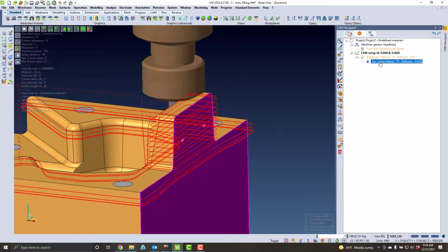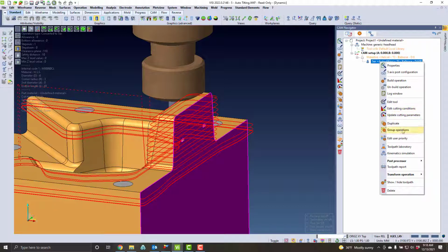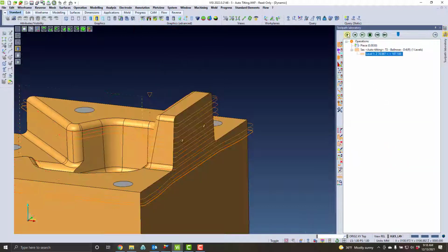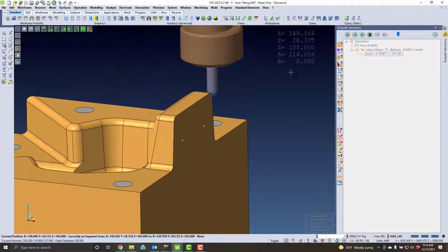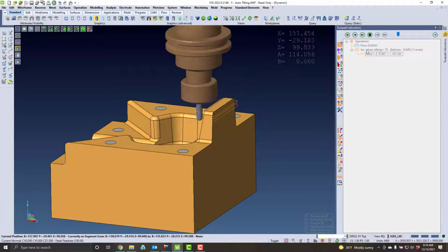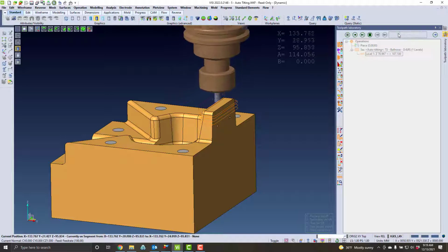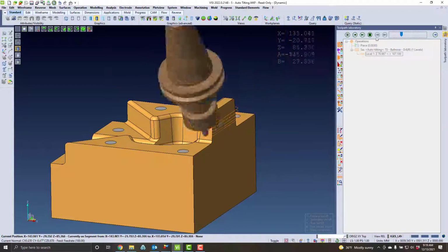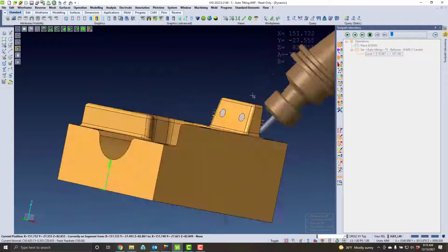If I run this within Toolpath Lab, you will see the auto tilt in Toolpath Lab and there are no collisions. This was very simple, just by selecting an angle, and the system automatically recognizes where it sees that holder collision and starts doing the auto tilt to keep the correct clearance. As you can see, it's automatically tilting where it is required.